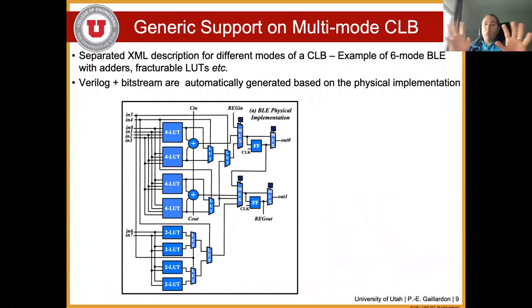And in addition to just supporting this basic description, it supports the notion of multi-mode descriptions too. Let me give you an idea about that. If you look at a real commercial FPGA, a 7 series FPGA from Xilinx, you have a fairly complicated basic logic element. It's a 6-input fracturable logic element that is composed of multiple 2-input and 4-input LUTs that get reassembled together with various multiplexers, to be able to implement either a 6-input LUT, or 2 4-input LUTs, or a full adder, that kind of stuff.